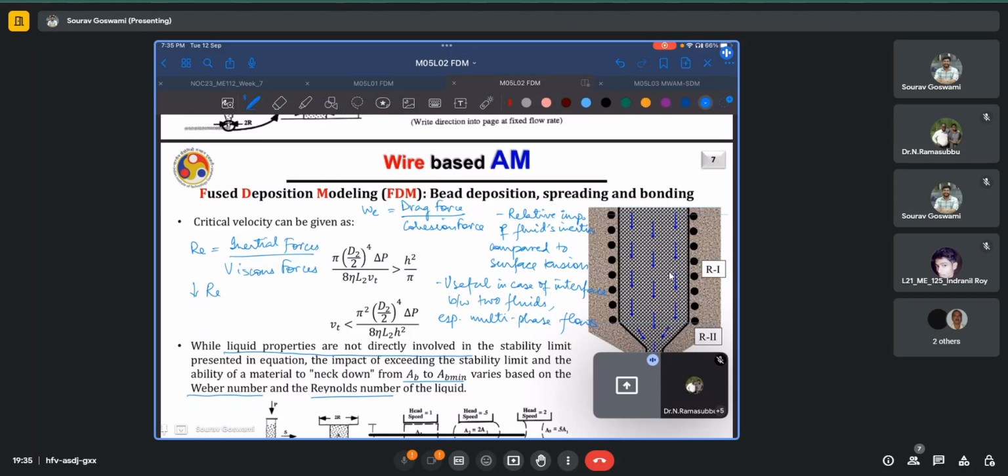So a low Reynolds number implies and is implied by a laminar flow. Whereas if I have a turbulent flow where the viscous forces are not so dominant, whereas actually the inertia of motion of the fluid is the dominant mechanism, for a higher Reynolds number, I will have turbulent flow, vortices, and other similar phenomena.